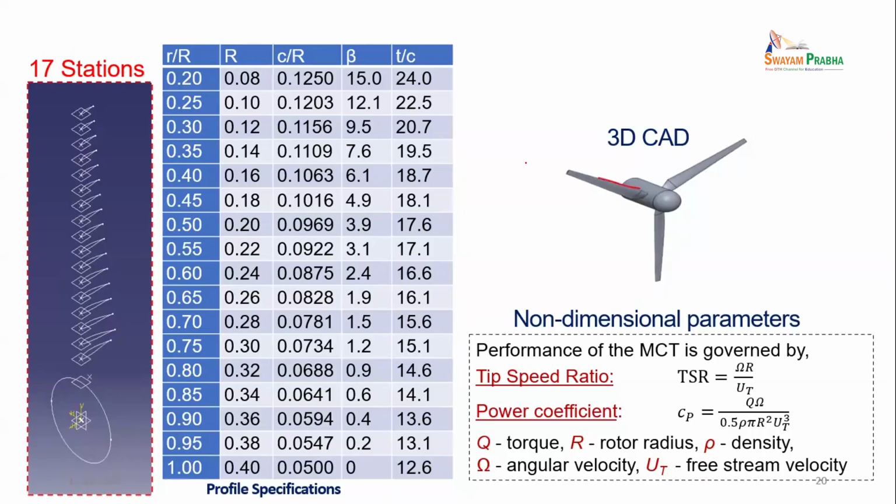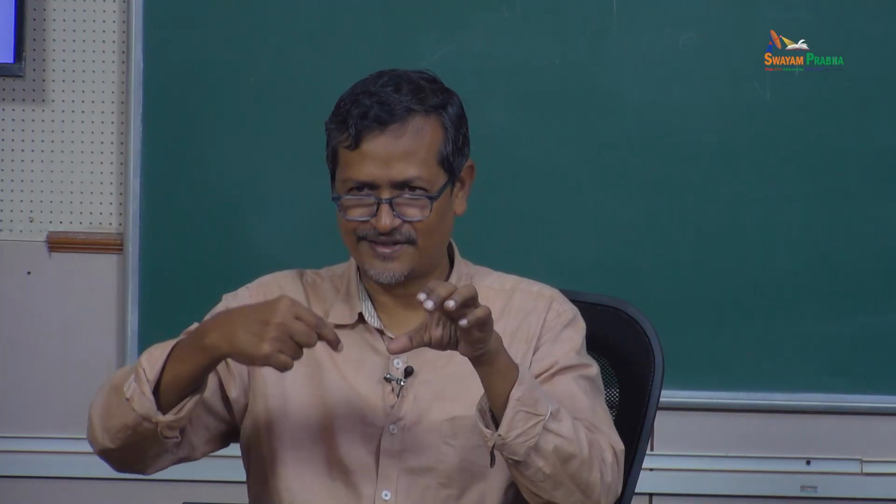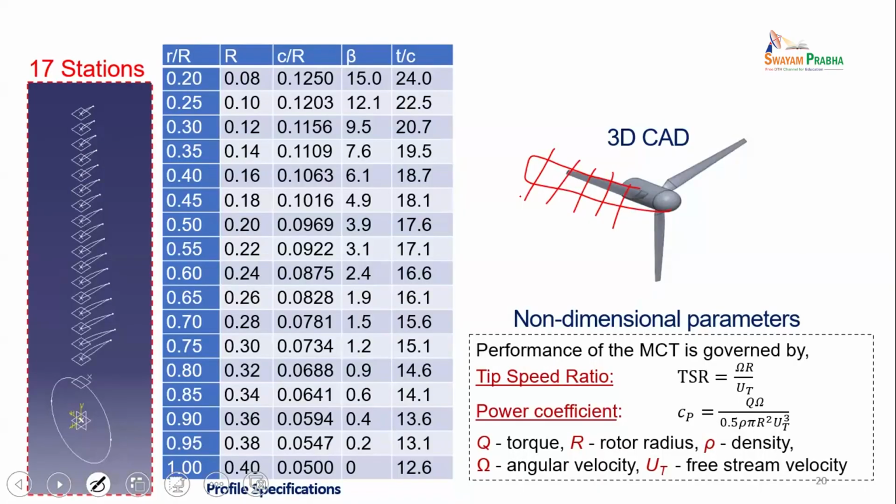A long turbine blade will be there, you can see this turbine blade. So, he divided the turbine into small sections, because the blade is larger at one end and smaller at the other. So, how the size is changing? Then he cut small pieces, he designed each part, then he lofted and made the turbine blade. Then after lofting, he made 3 turbine blades, then he did all the simulation.